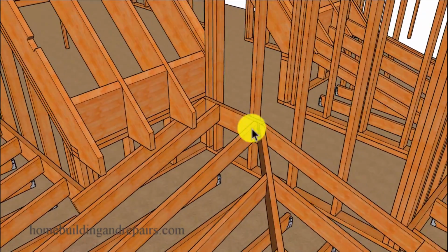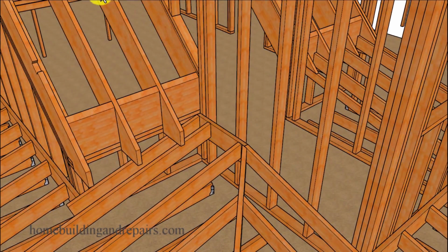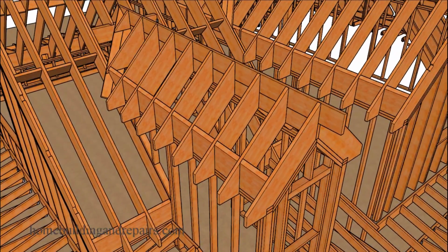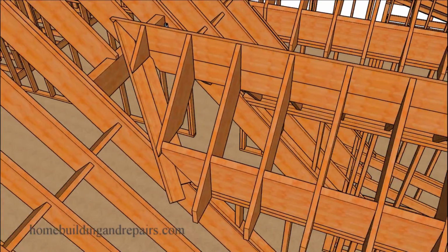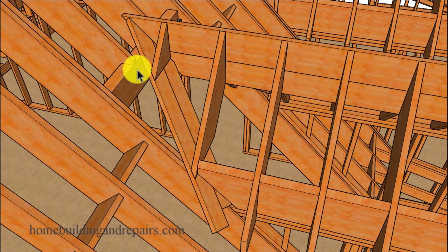This will not be a ridge since it is going to be nailing into a wall. And we are going to be using 2 boards instead of 1 long board for our ridge here, along with shaped blocks over the exterior wall framing. And this building will have a flat soffit all the way around. And you could always install some backing here.